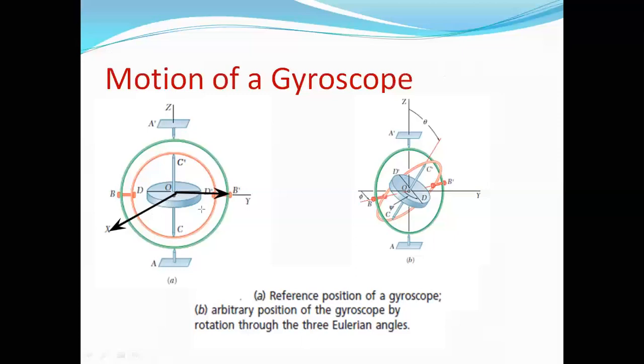If you look at this capital X and capital Y axis, they are also the axes of symmetry, because they divide your overall system into two symmetrical portions. Now, as far as the axes of symmetry are concerned, the axis of symmetry happens to be what we call the principal axis. The axis of symmetry is the axis over which the product of inertia is equal to zero.